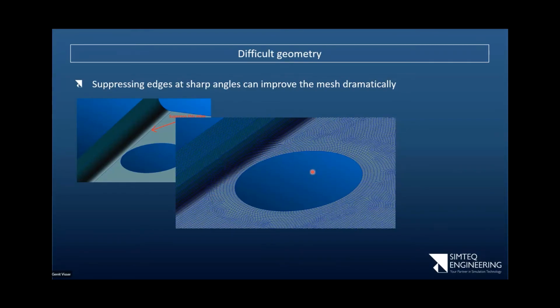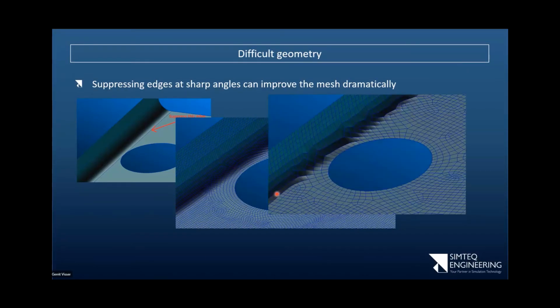Actually, the mesh in general looks a lot better, except we unfortunately now end up with the warped kind of elements in this region. Anyway, mesh coarser, even with the coarser mesh, you see the warping a bit more, but still this allows, whether it's fine or coarse, to have better elements in this region at least. I don't have those collapsed elements.